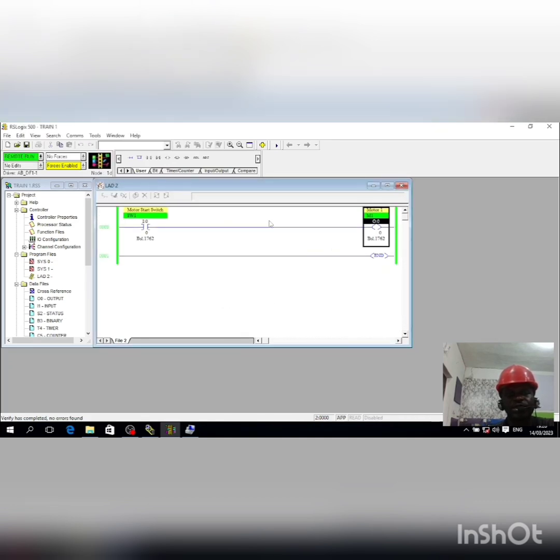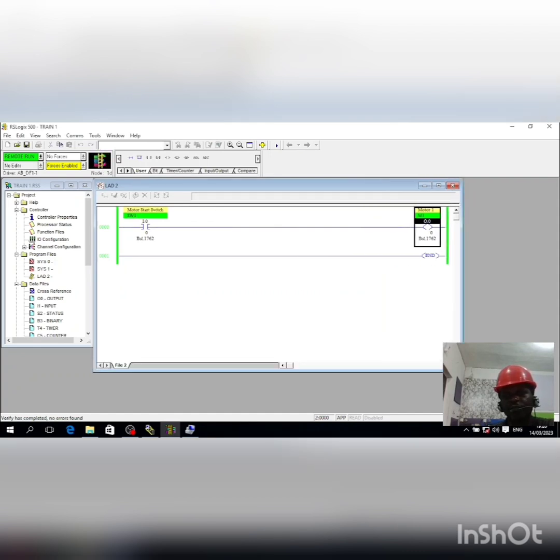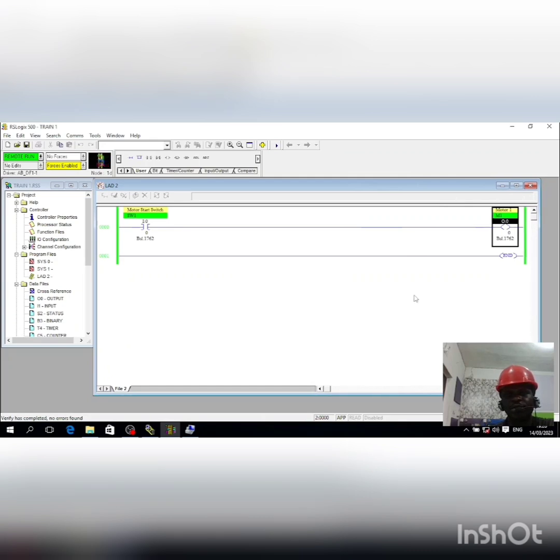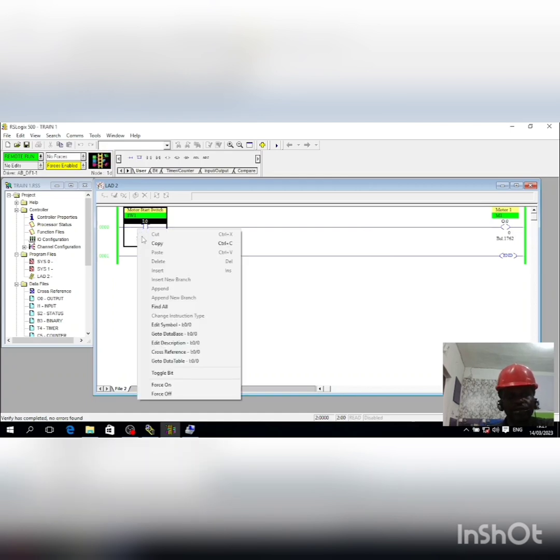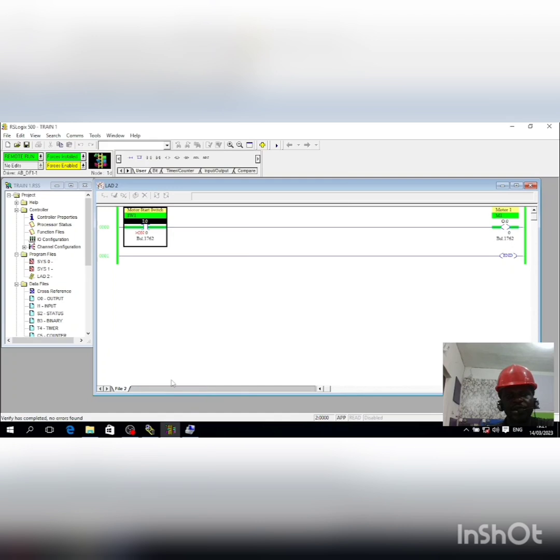Yes. Okay, so you see now my PLC is online. As you can see, I am online with my PLC now. My program is online now. I can force this instruction now, and we see that this will be energized. Okay, it's currently off now. Examine if closed, it's currently not closed. If I force it closed now, say on. Okay, it's forced closed now. You see that here it's on now.